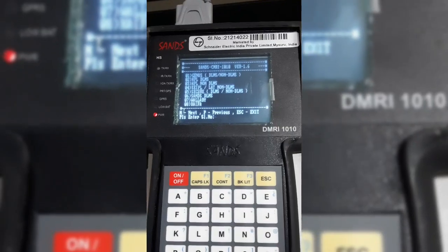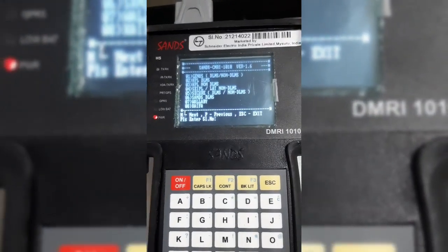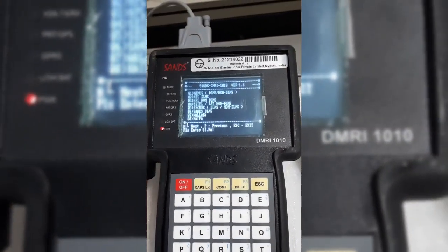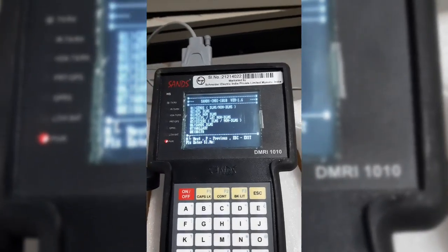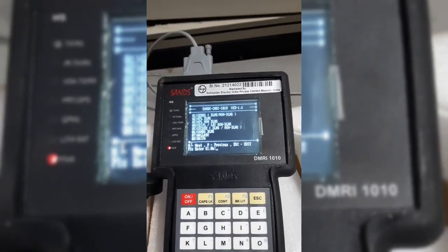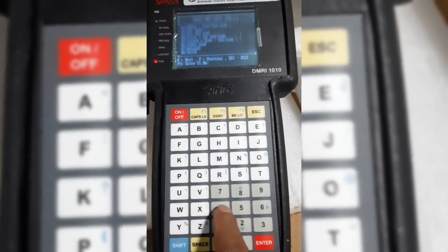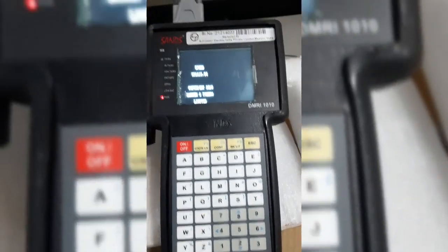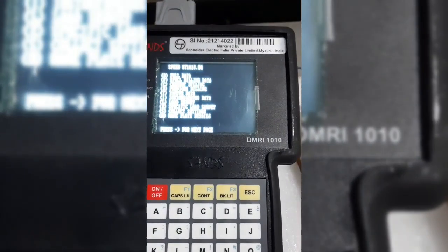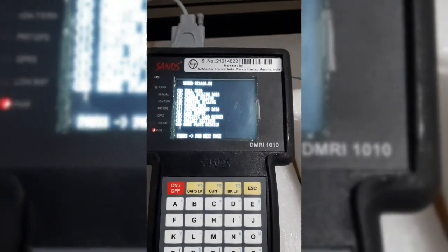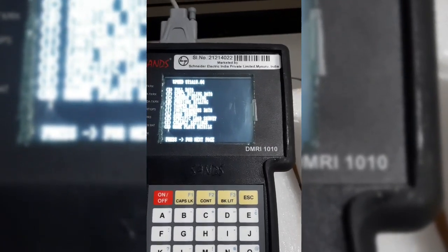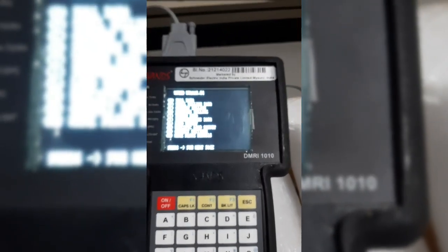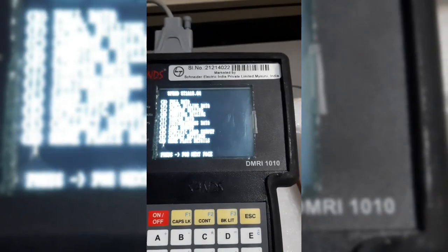So we'll go to option number 4, called SEPIL or the LNT non-device language message specification, that is non-DLMS. We'll go to option number 4 by pressing 4, and then I'll press enter, and this screen will pop up, and then we need to download the full data, the full energy meter reading. So we will have to press D.